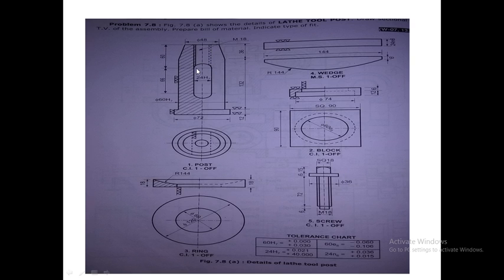And since this is a slot or a hole, this will be visible in section and in without section also. Now the length of the slot is equal to 24 mm. You can see the length of the slot is equal to 24 mm, because in this slot we will insert the wedge. Now you can see the top view of the wedge. The top view of the wedge is given as the width is 24 mm, so this wedge will fit inside this slot. In assembly we have to match the dimensions and see which part will insert inside the other part.